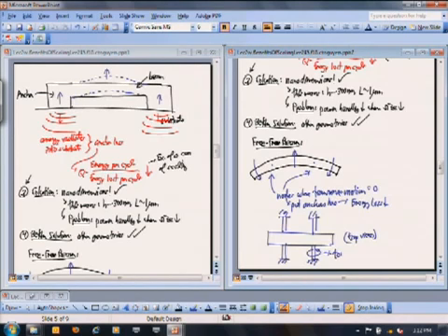Turns out the energy loss design is simple transmission design, transmission line design. All EEs know how to do that. Maybe some MEs do, right? But it's a mechanical transmission line. You design it to be quarter wavelength. You knock out all the energy losses to the substrate. Okay, so there's where circuit design really helps this thing here.